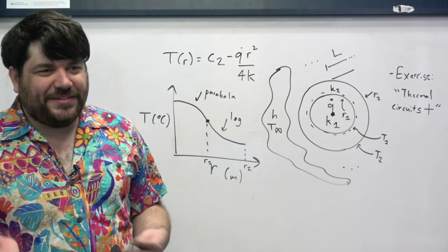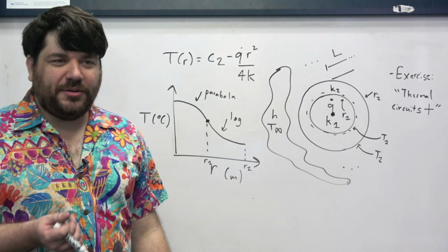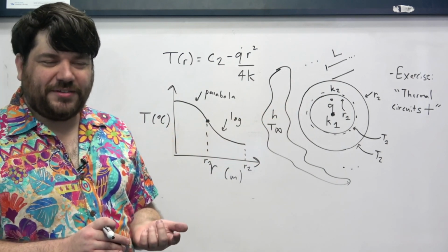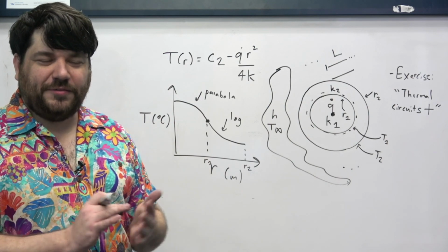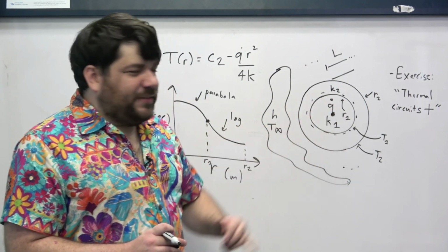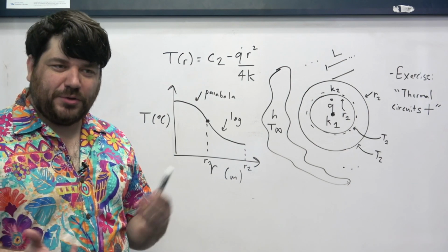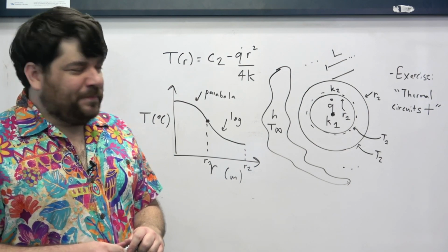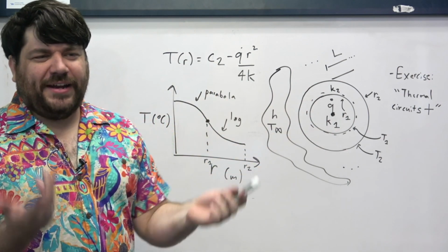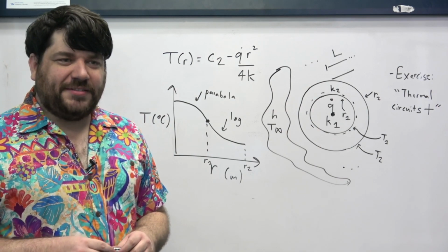Does that make it seem like the heat transfer rate everywhere inside of the cylinder is equal to 0? No, because we have the q dot, which means that the heat fluxes and the heat transfer rates aren't conserved as a function of r. So this is only happening because of the q dot. And so this is a perfectly consistent and nice description of what the temperature profile looks like inside of the system. And we already figured out how we can calculate the C2 for the temperature in the core and how we can calculate the constants for the temperature profile inside of the cladding as well.